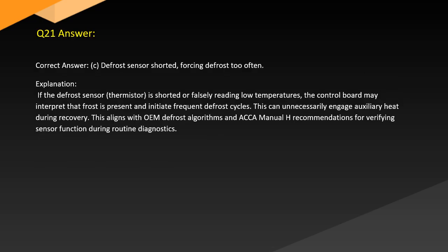Answer. Correct answer: C. Defrost sensor shorted, forcing defrost too often. Explanation. If the defrost sensor thermistor is shorted or falsely reading low temperatures, the control board may interpret that frost is present and initiate frequent defrost cycles. This can unnecessarily engage auxiliary heat during recovery. This aligns with OEM defrost algorithms and ACCA Manual H recommendations for verifying sensor function during root diagnostics.